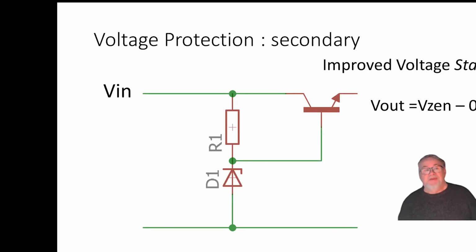And a big beefy transistor like that only costs, you know, £1 or whatever, and that's a good solid voltage stabilizer. But it's not a regulator. It'll set the voltage and it'll keep it there. If the current drawn by my circuit goes up or down, then the voltage there, as the more current's drawn, the output of that transistor will droop.